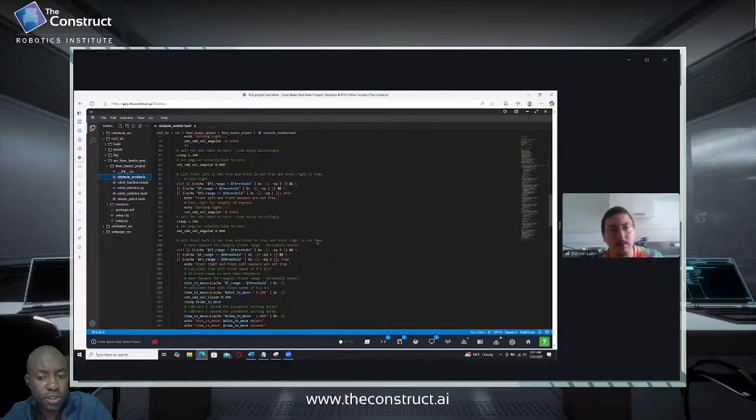Okay. So you're speaking with regards to maybe taking into consideration, right now you were using eight laser indexes. So if you were to use 16, it would be better. Is that where you're going with this? Yes, it's with the logic as well. I have to use the logic to make sure that the turn needed is only a smaller turn, or the turn needed is large, depending on how many sensors are blocked.